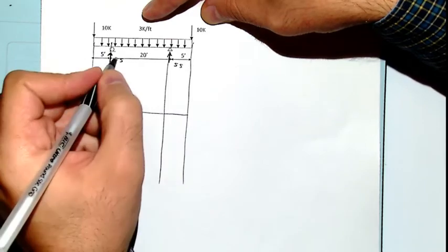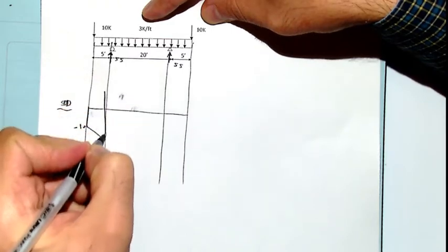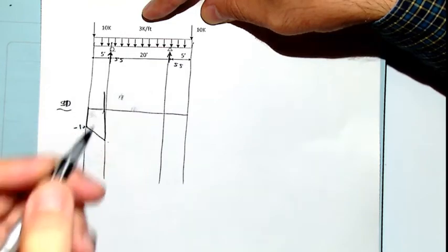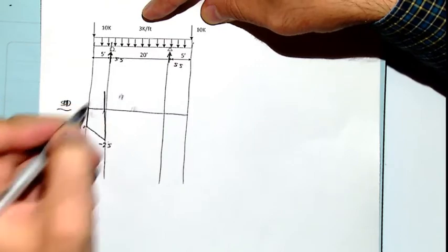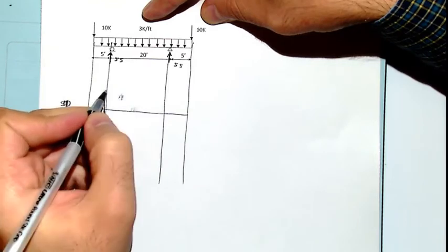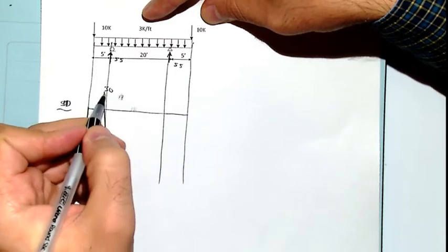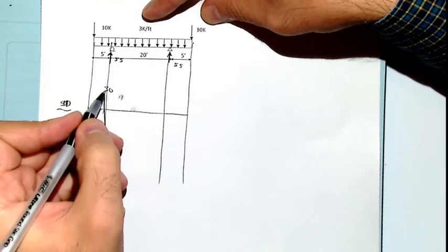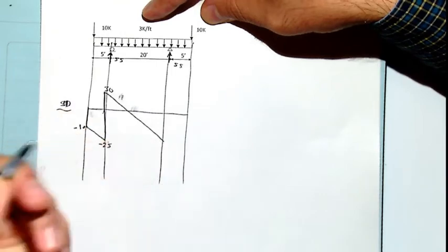Actually, it's not an external load. It's 55 going upward. There's a jump here, and minus 10 after that here, and this value is minus 25, and this value here is minus 25 plus 55, this range, it's going to reach 30. And after 30, we're going to have a downward straight line, order 1, so we're going to draw a line from here to here.